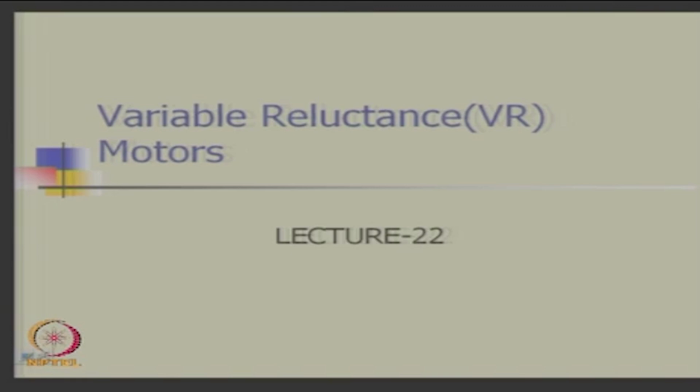Okay, today we will start with a new topic on variable reluctance motors. You may be considering that almost all the machines that you generally discuss, you take it to have a constant air gap, right. The length of the air gap is the same, which would mean the surface of the stator and surface of the rotor are cylindrical. Now, the motors that we will now be discussing are those where the surface is not smooth. That means there is saliency or variable reluctance.